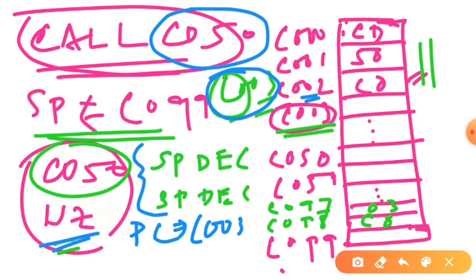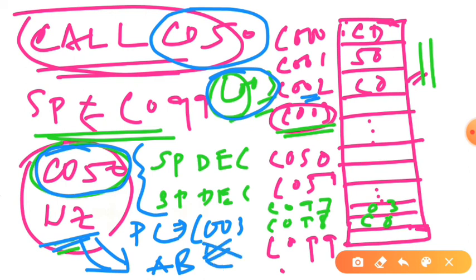Now the content of the program counter, C003, will not be placed in the address bus, which is normal during the execution of any instruction. But in case of jump instructions and call instructions, this doesn't happen in this particular machine cycle. Instead, the content of the WZ register pair, which is nothing but the target address, is placed in the address bus. The content of the program counter is prohibited from being placed in the address bus.